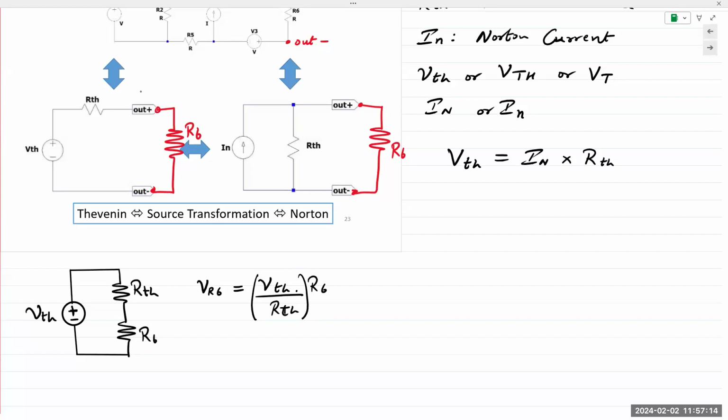Again, the important point is we had R6, we removed R6 from the circuit, we analyzed the rest of the circuit independent of R6, and we obtained that voltage source, Thevenin voltage, and the Thevenin resistance. Okay, R6 is not part of the analysis. Very important to remember that point. R6 is not part of the analysis. You're analyzing the entire circuit independently of R6. And this is assuming, of course, the rest of the circuit is not changing, which in this class it won't.